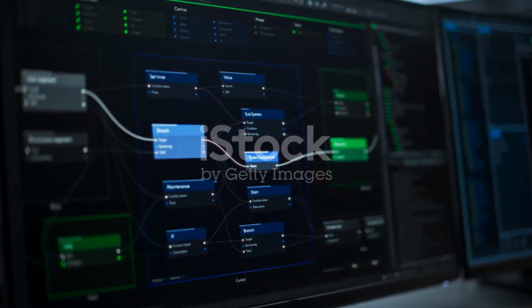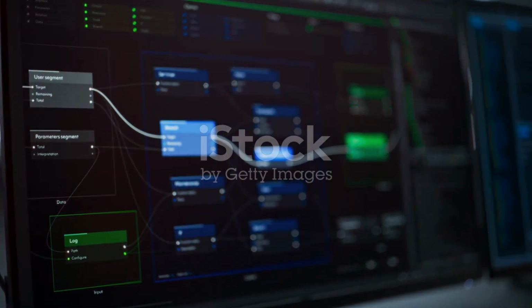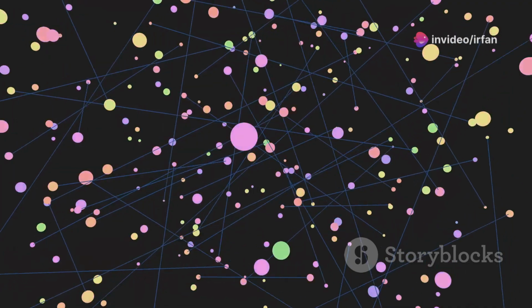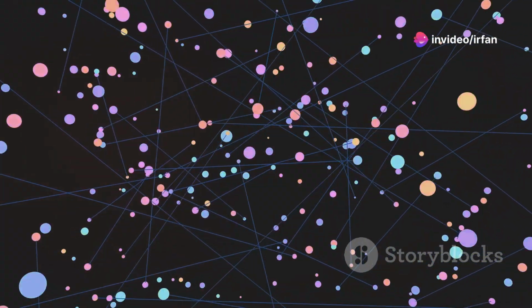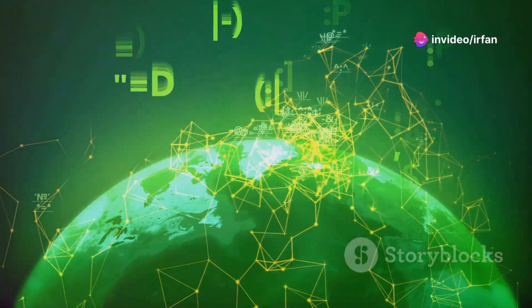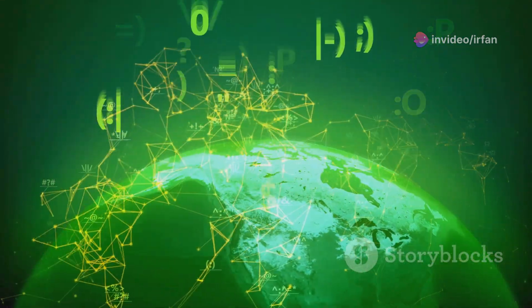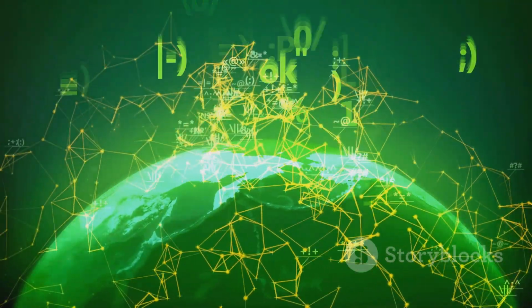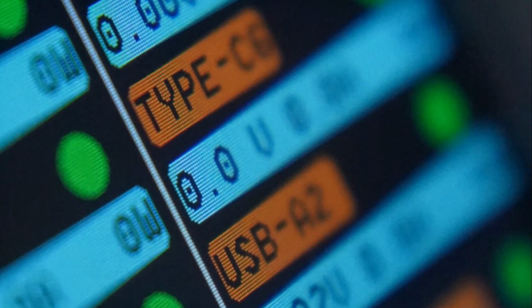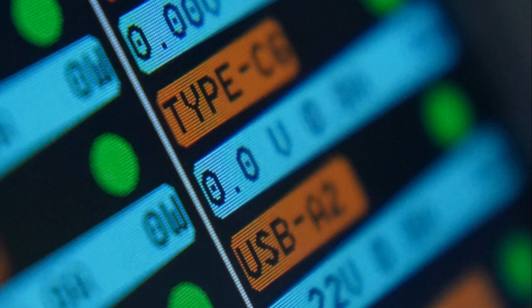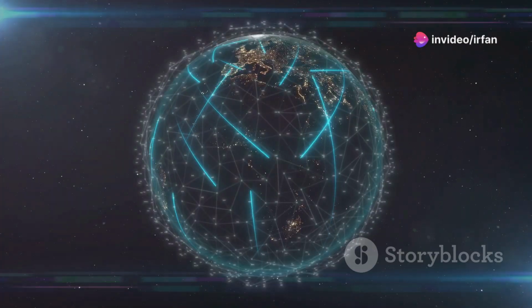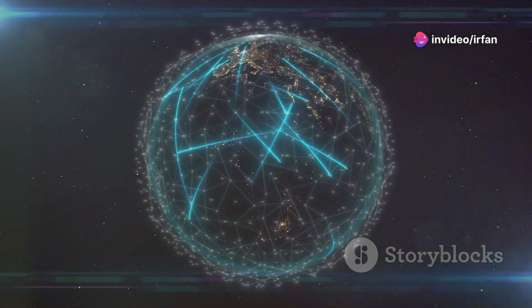Understanding nodes, connections, and graphs is essential to harness the power of Dynamo. Nodes are the building blocks of your Dynamo scripts. Each node represents a specific function, operation, or data input/output. They are visually represented as boxes with input and output ports. Connections define the flow of data between nodes.